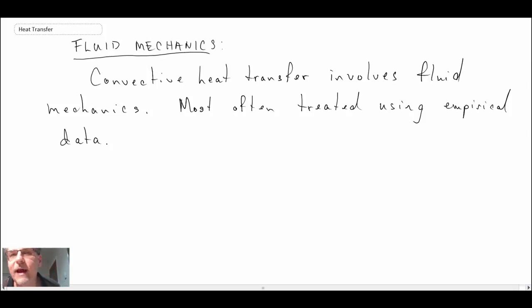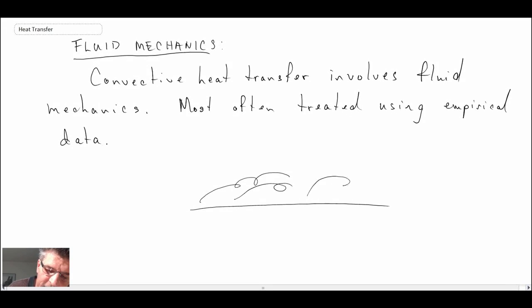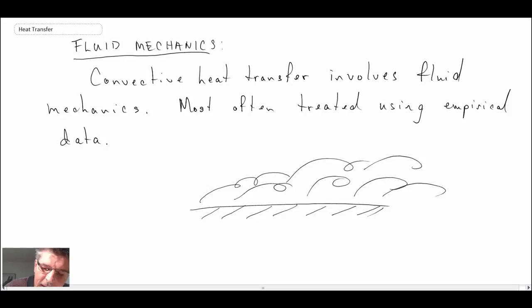So in this class, we'll be taking a look at convection. In the course, we'll be looking at both natural and forced convection. Natural is where the buoyancy force is what is driving the fluid, and that provides the energy exchange. Forced convection is where you'd have a pump or some sort of fan or blower moving the fluid over the surface. We can do analysis up to a point. We can do laminar analysis, but as soon as you get complex shapes, and if you get turbulence forming in the convective heat transfer over the surface, so let's say you had a turbulent boundary layer here, then all of a sudden it becomes very difficult to predict what the heat transfer rate is.